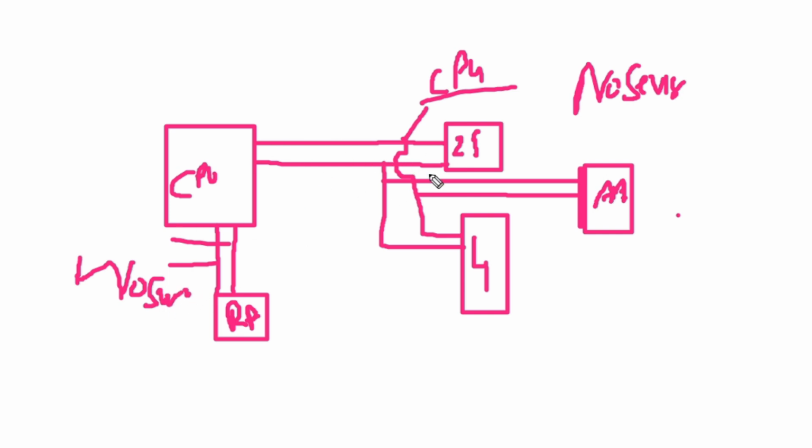But the difference is that these three communication lines work differently from the transceiver IC. You will see some components in them, for example a resistance. Suppose this 4G PA data or clock line breaks for any reason there.